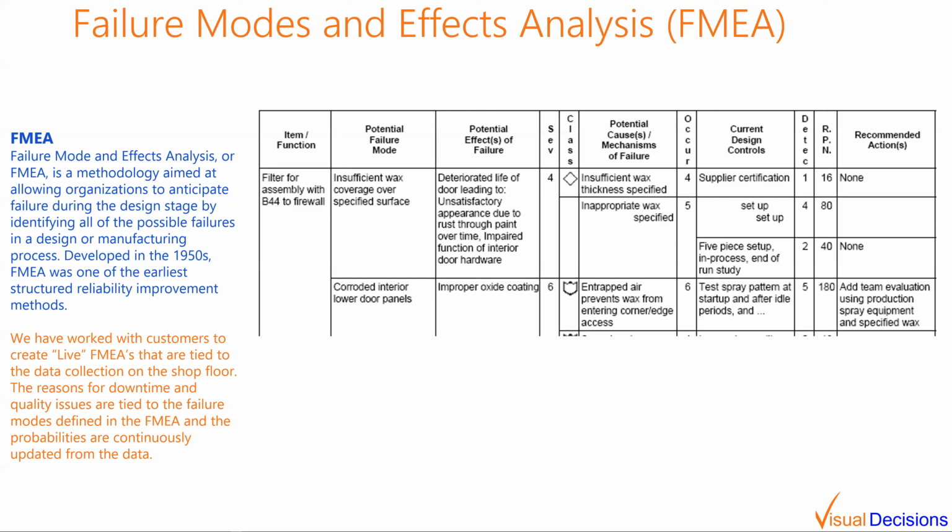But if you're capturing that information on a 24/7 basis, and you're going through and you're assigning causes to those failures and so forth, if you've done an FMEA already, you can actually utilize these failure modes and causes of failure as your failure tree that you're capturing that information against, rather than just setting up downtime reasons within the process or within the software and having that completely dissociated from the FMEA analysis that you've performed. You can actually link those together and utilize those FMEA root causes as the things that you capture information against. Just train your operators to look for those different things.